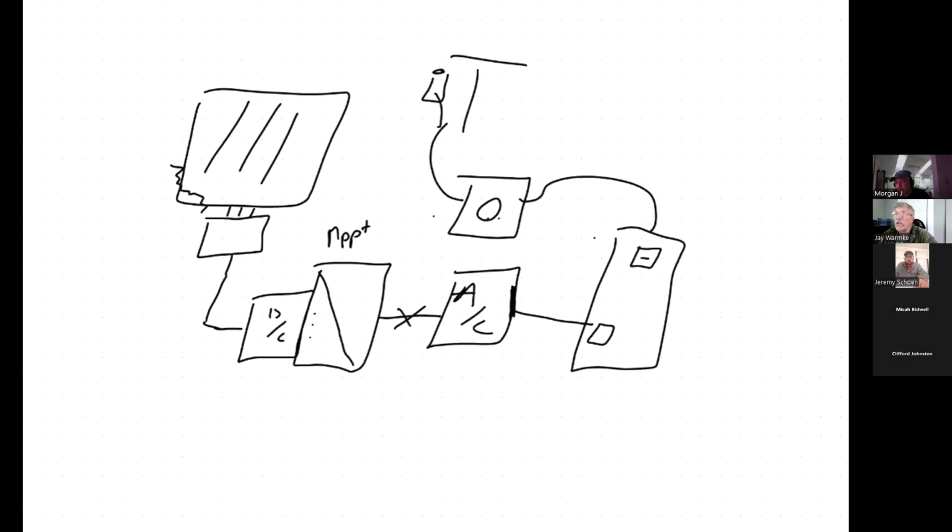If you're connecting into an individualized MPPT, they can be different. They could be slightly different voltages, slightly different amperages for sure. You'd have to just check the specs on the inverter that you're connecting to. That's one of the advantages of a microinverter: you could have different sized panels. You can have one 300-watt panel, one 350, one 325. They could all be mismatched and they act independently.